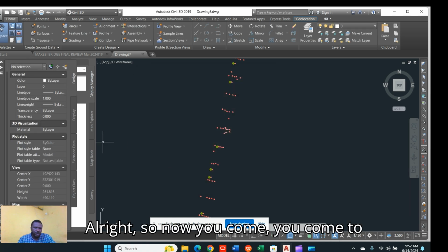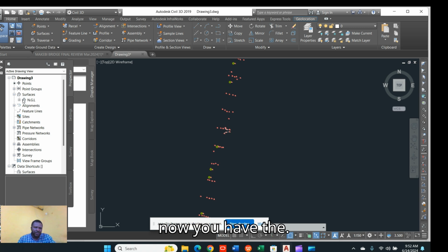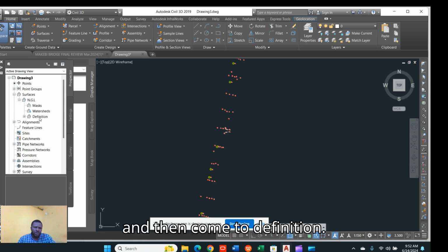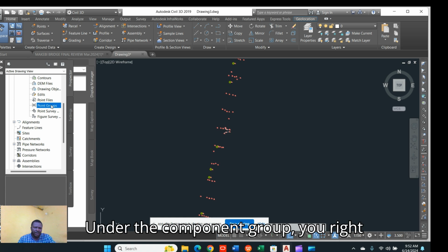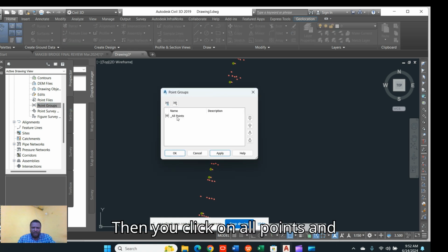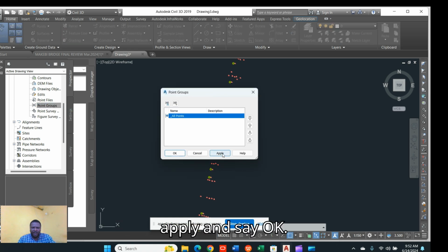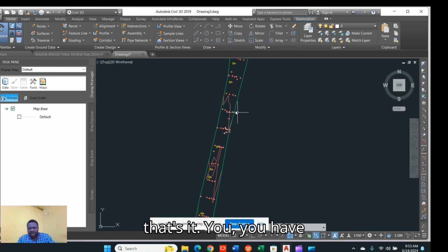All right. So now you will come to this place and then come to the surface. Then you can see now you have the NGL opened. So you can click on the NGL and then come to definition and then you come to point group. Under the point group, you right click and click on add. Then you click on all points and apply and say okay. Now click on the surface and that's it.